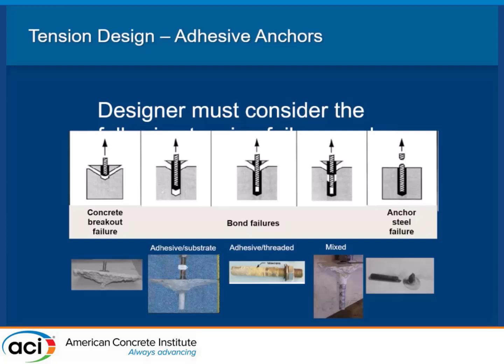And as you can see here, and this is what I want to start showing you, is a lot of pictures. If it's done correctly, you get your standard looking concrete breakout failure. This is a case where we lost our bond in the lower half, and then it bonded in the upper half, and so we didn't quite get everything we had.